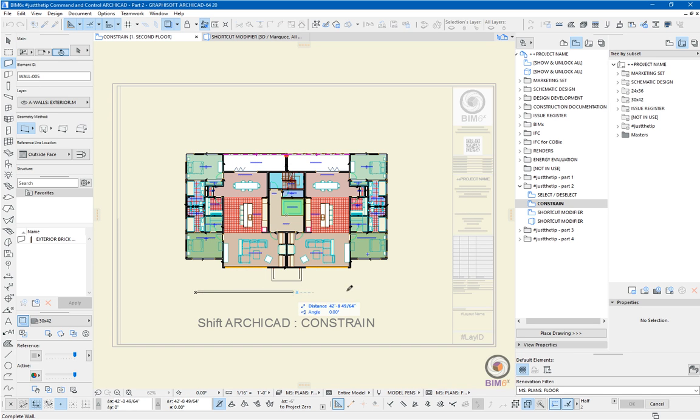And what that does, I'm holding it down just now, you see wherever the mouse goes, the wall is actually constrained to the horizontal in this case. If I let go of Shift, let it come round to a different angle, we can do that again, or we can slide up and down and just choose anything else. So it's actually quite useful.